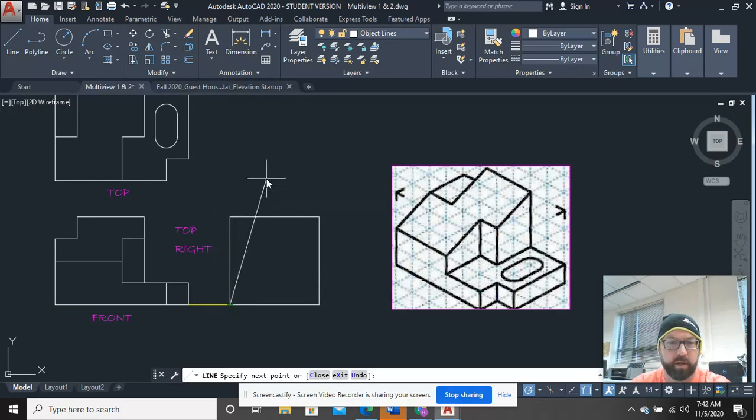and I'm going to come over, all right? And this one I think is pretty easy because we have this shelf area, which comes up 1. So I go offset, 1, all right? And we can't see anything about the hole right now, but we can see that this face along the right side of the object is split, right? Part of it projects out and part of it projects back. We can't see the projection, but we could see the edge. If you look where it's at 2. So I'm going to go offset 2, right?